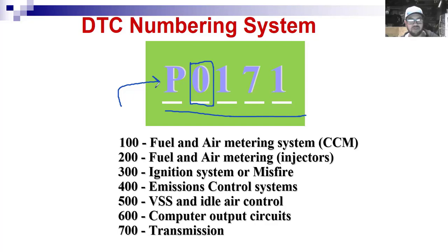We can get computer codes, network codes, and stuff like that, but mostly what we're going to be accessing is powertrain related. But there's still a ton of diagnostics, and it's the really important stuff of why does my car not run correctly, right? So remember that if you have a generic code, the second digit is a 0, it doesn't have to be specific. You could look up any OBD2 code chart and find the definition of that code.